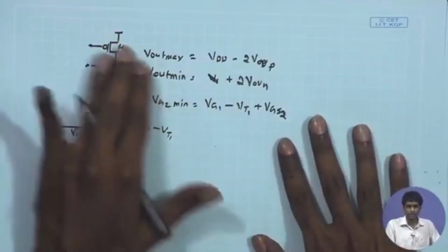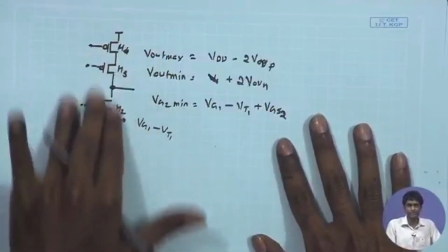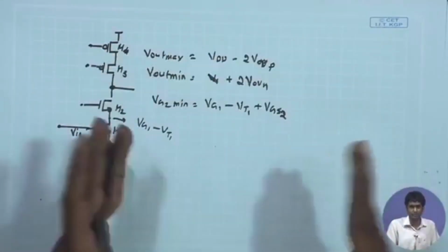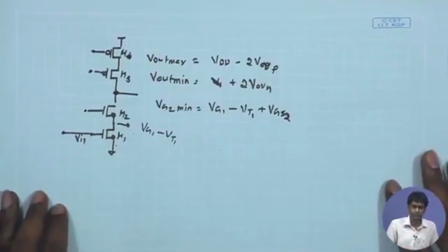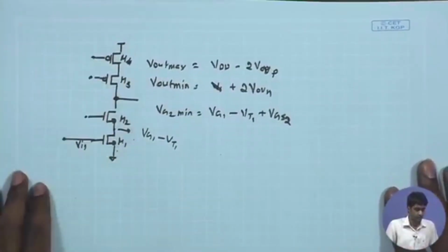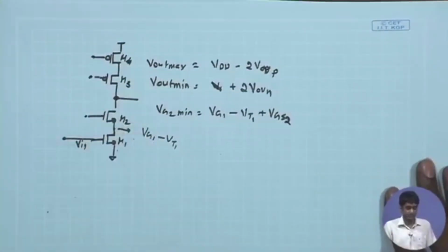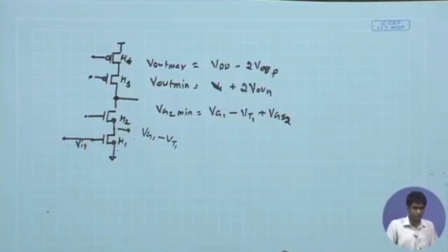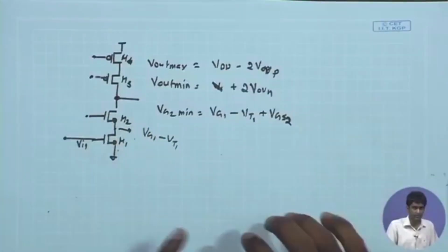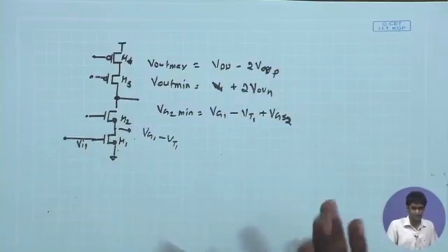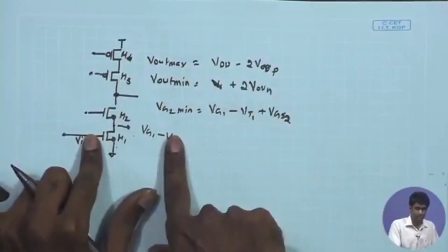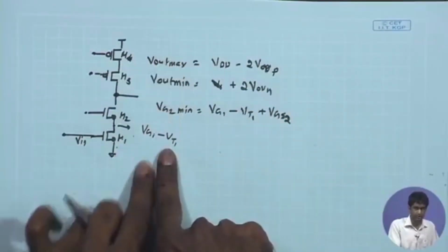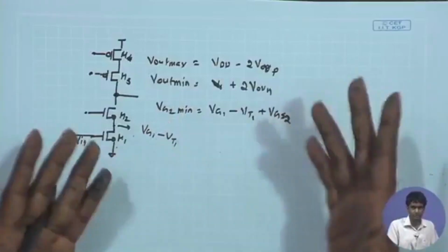So, we need to take care of the closed loop operation if we are applying the differential scheme for this cascode for realizing op amps and building feedback amplifiers with the help of this high gain stage. Let us straight ahead go to the differential scheme, which should just imply that we use another alternate branch, the differential branch, and put a current source over here, just like we do for the simple common source stage.